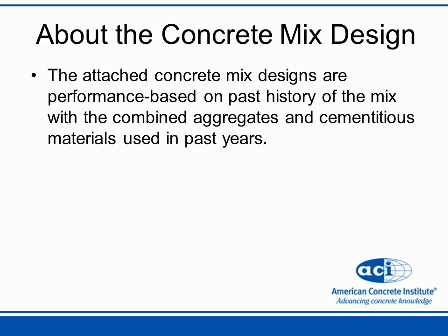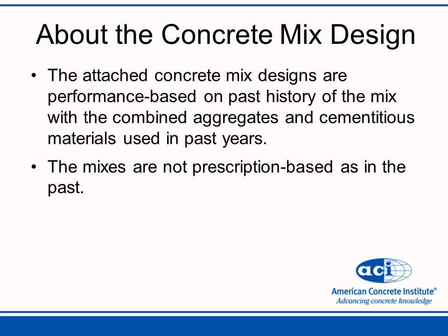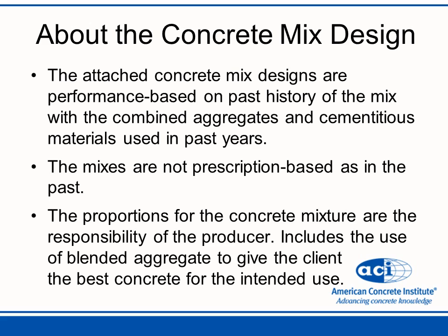All the mix designs that I did when I was with Gallup Sand and Gravel were combined aggregate gradations, and based on past history they had the same fly ash and cement over a number of years. The mixes were not prescription based. The proportions were my responsibility as a producer. I took that responsibility. I included a blended aggregate to give the clients the best concrete for the intended use.